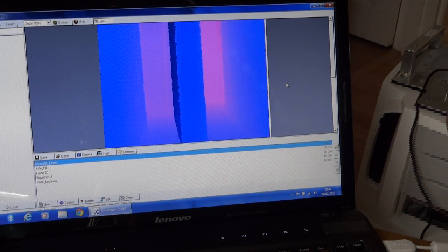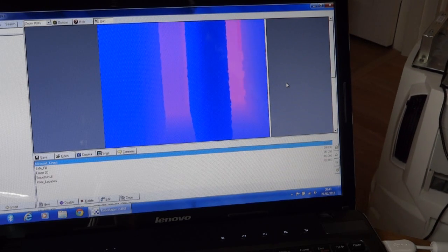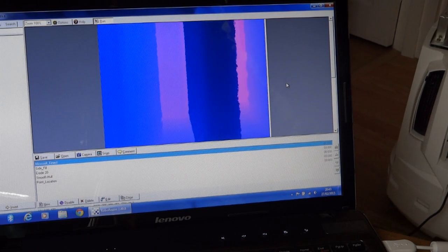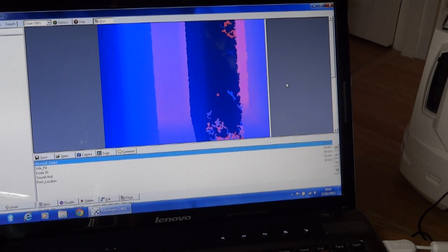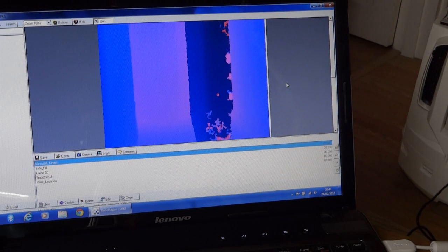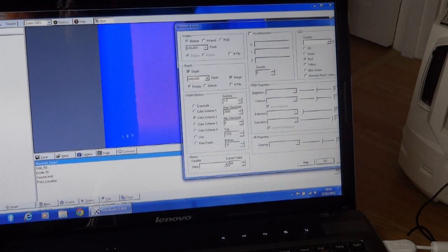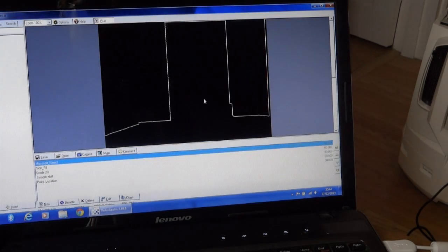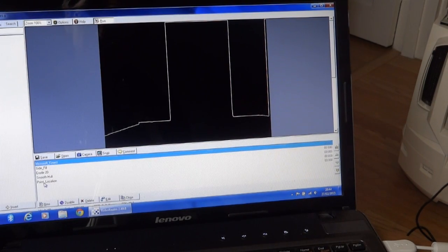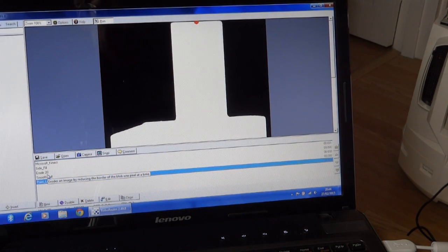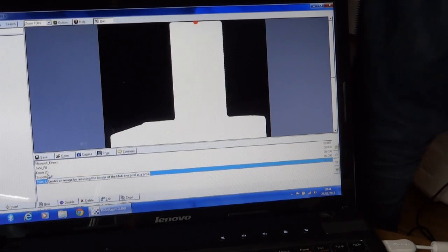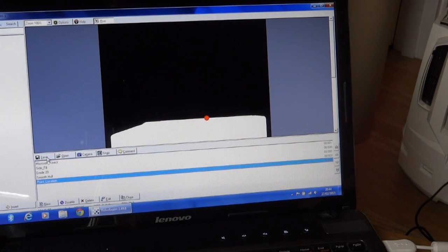If we come back again and I push the robot forward, things all go bad and the picture breaks up, and that's because we're within the minimum range of the Kinect. So at that point the laser line goes wrong and shoots to the top, and then obviously my processing's broken because it immediately thinks something's really far away. So if I were to take that object away, well, that's not terribly good either.